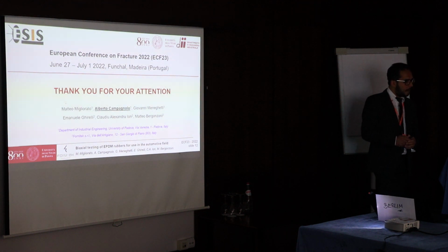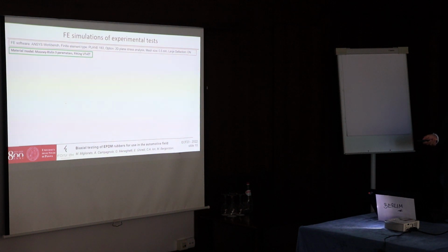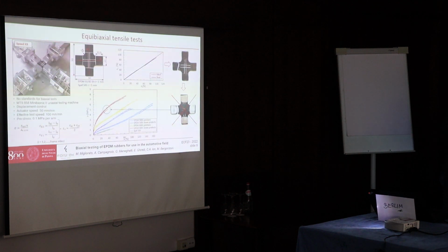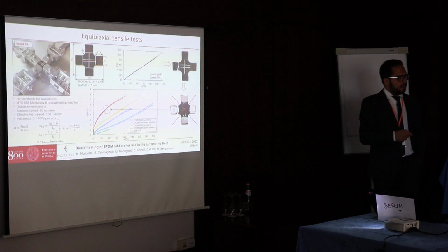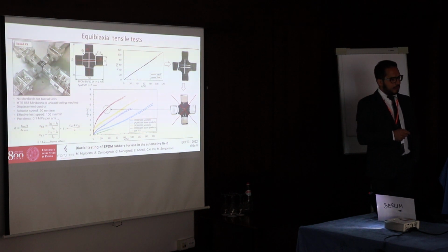Thank you for your nice presentation. Like you said, in the biaxial test, the fracture happened close to the grooves. We did a study on dual phase steel and mild steel, which is a different material, of course. But we did optimize in AutoForm along the radius that you have, if you make a further cutout, as you can see. I can share the reference. That reduces the cross-section area in the middle compared to the grooves area. Maybe you will not go all the way up to failure, but that will improve the maximum strain.